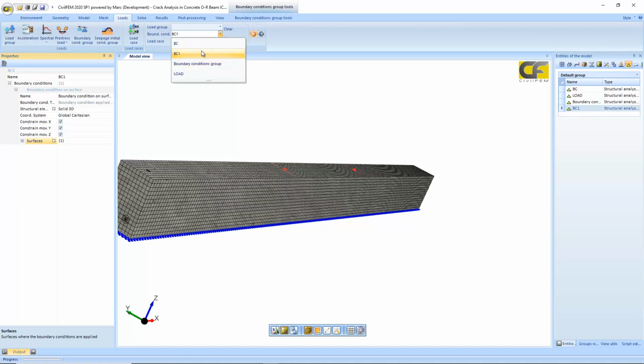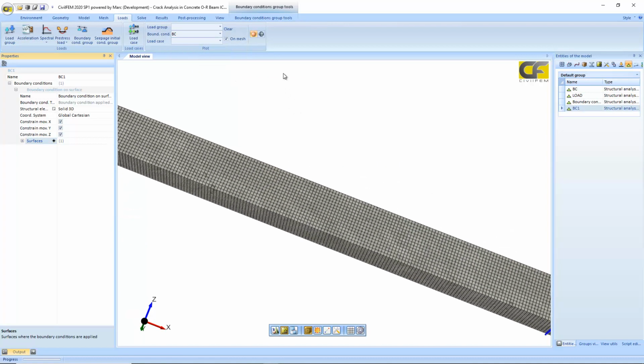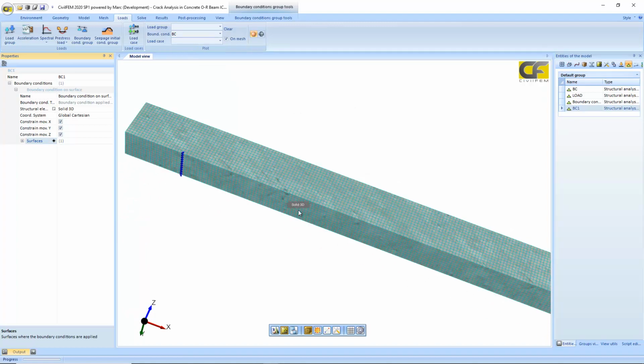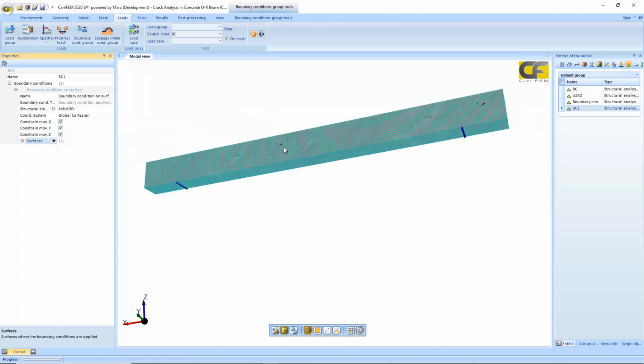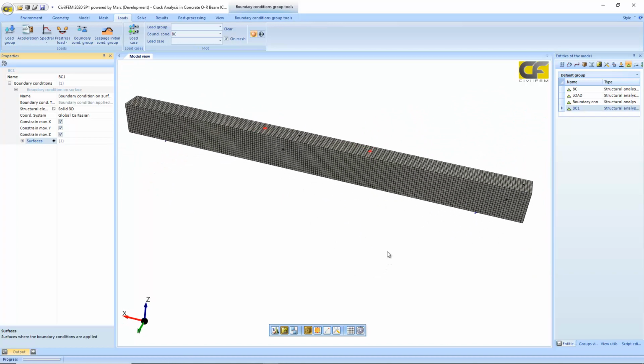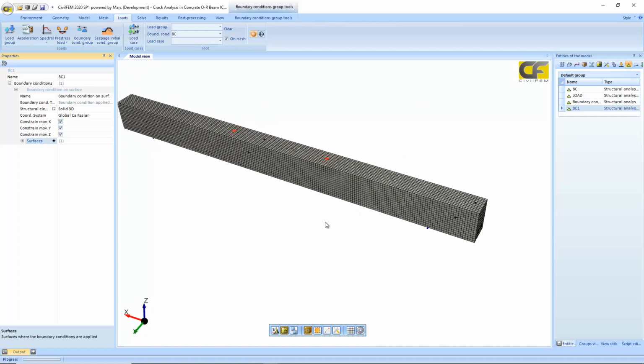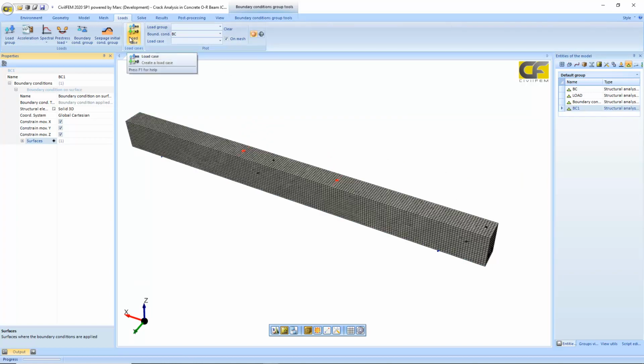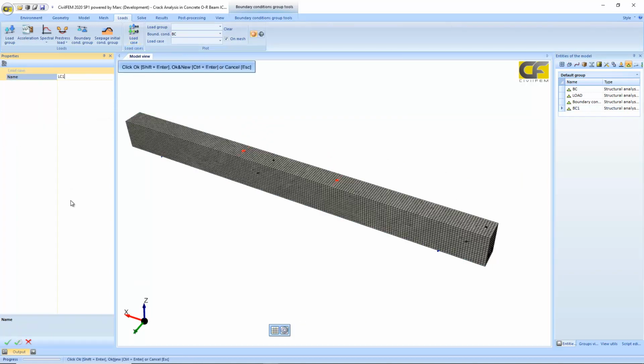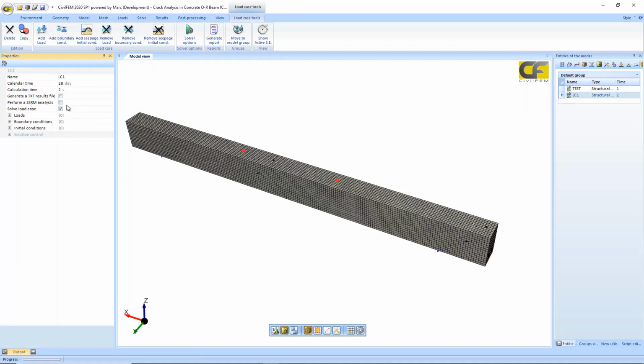We have selected these two lines as the vertical supports. Important thing here is you can define as many different boundary conditions as load groups, but the software will only solve the different load cases defined. Set a load case. Here in the load case, we combine the different load groups that are defined here, the different boundary conditions, and you can add them here. Unless you define a load case, you won't have results.